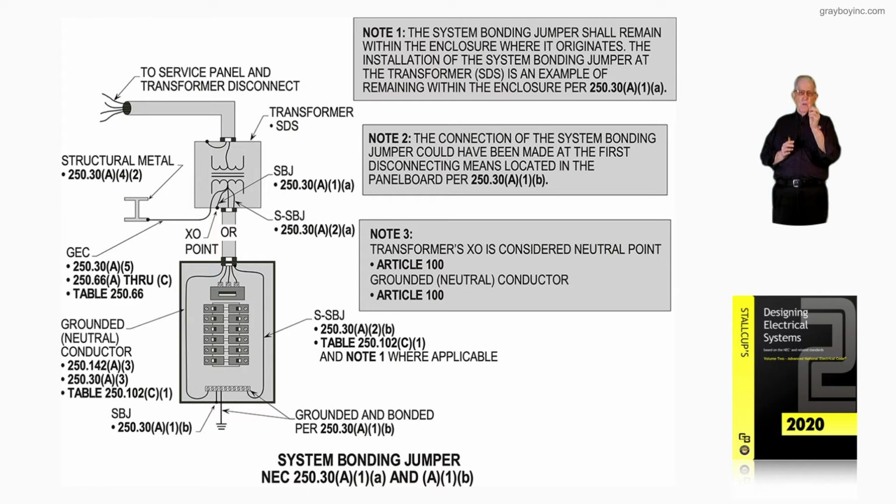But notice the grounded conductor for an effective ground fault path is sized, and you've got the sections there. But if it's a neutral, then you'd have to go to 220.61, remember, and it would have to carry the maximum unbalanced load. And if I'm an electrician, as we said, if I see 150 amp neutral load on L1, 140 on L2, 130 on L3, the neutral has to carry the maximum unbalanced load on any phase, so it'd be 150 if I lost the other two legs. So that's what they're talking about here. And then, of course, you see the supply side bonding jumper bonding two standard lock nuts and a bushing would also be number 2 from that table, 250.102(C)(1).